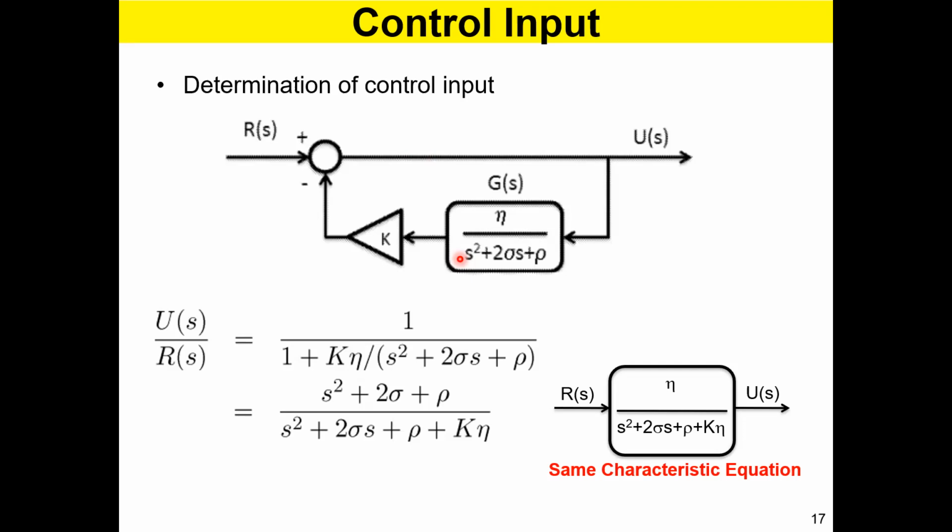We do all these things before we actually build the system. If you have the system already, you can just measure it. But this is the design and verification phase, so there's nothing out there in reality. We have to do everything on paper, on the computer. So we get the signal, which is the difference between RS and the response, and that signal now looks like the response. Therefore, any other block beyond that point will have to go to the feedback. So it's a new system now.